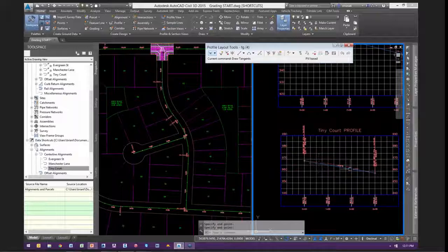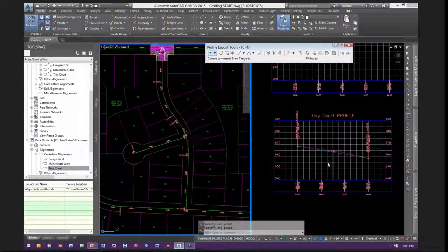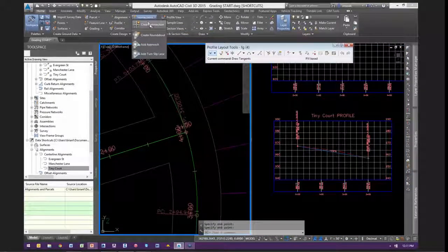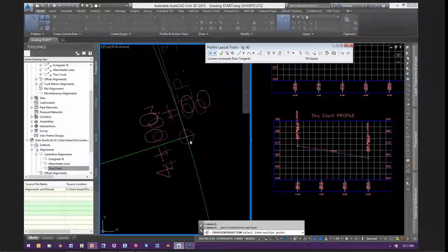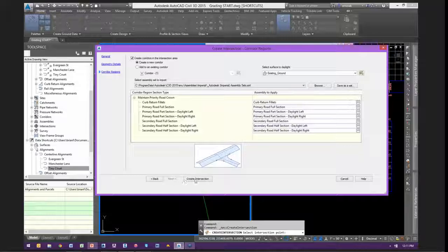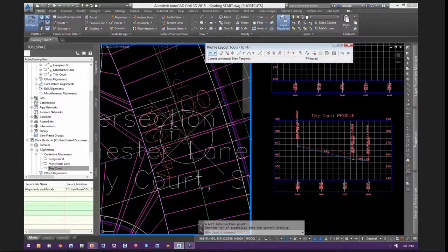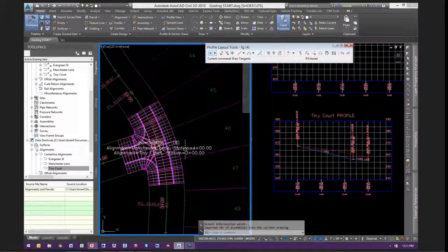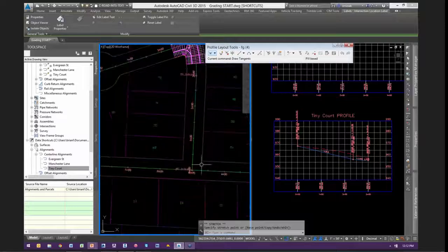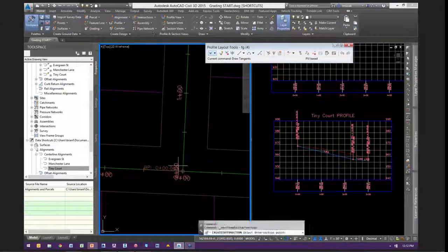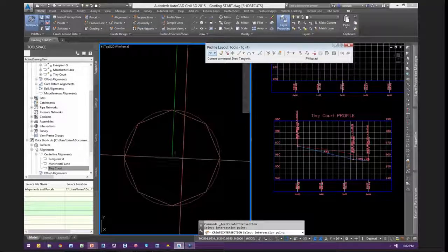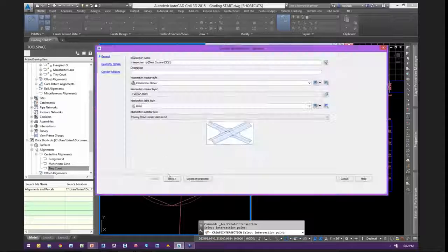So we're draining out of that cul-de-sac back towards the intersection. The intersection tool, of course, will lock that profile to the primary profile. So let's give that another try. There it is. So again, taking the same default parameters, we're not focused on detailed designs, but again on workflow. So there's a second intersection, and I'll go ahead and make my third one down here. And this one I know I have both alignments in there, just got to get the right intersection.